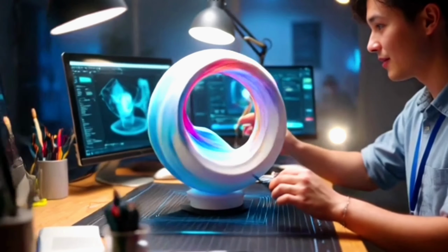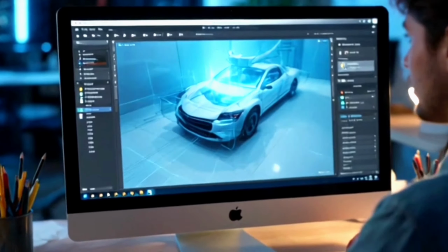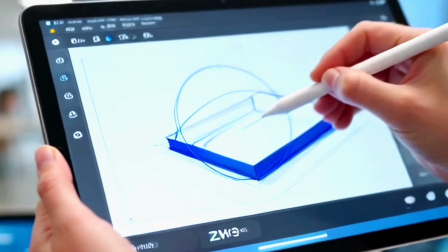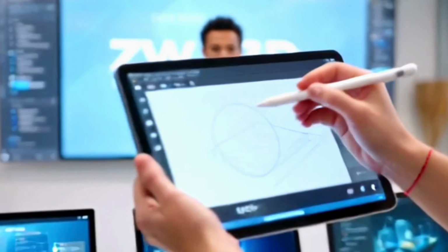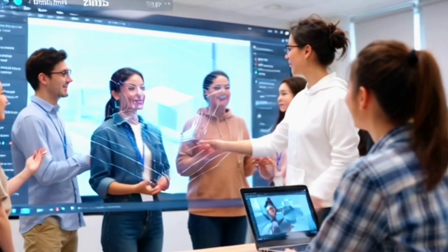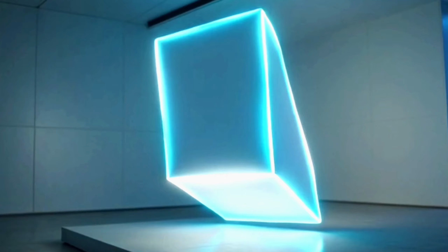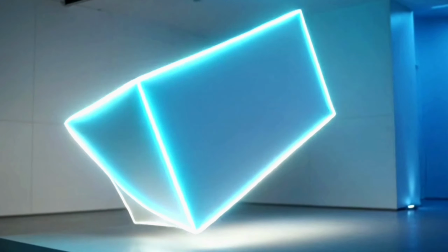Before you finish, verify your dimensions one last time. Does the 50 mm height in the front view match the scale of your top view? Are your arrowheads sharp and touching the extension lines? Mastering these sectional details is what separates a student from a professional designer.